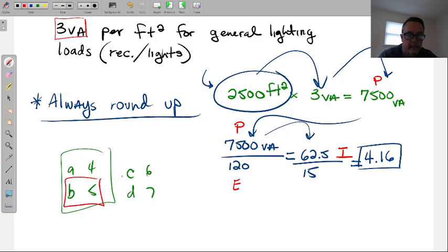It is a physical breaker, which we have to account for, because that fifth breaker is dealing with some amperage. Now we're going to try to divide these 62.5 as evenly through 5 breakers as you can, but that will be hard. And remember, this is an imaginary 62.5 based off of an estimated calculation, so it doesn't even exist, really.